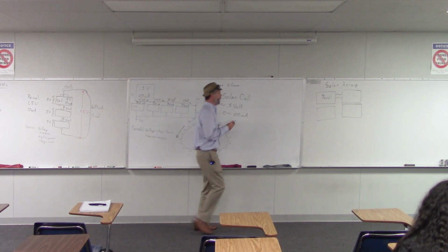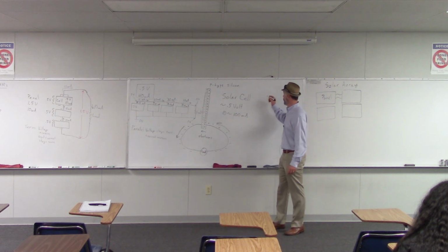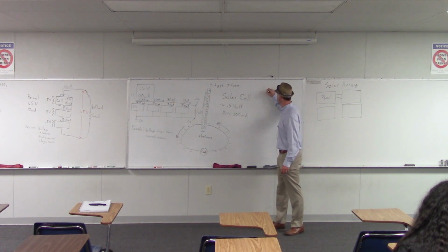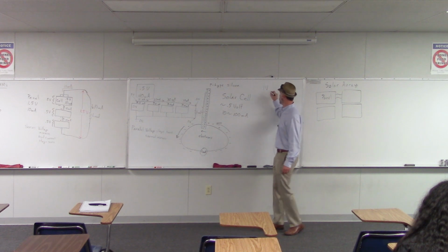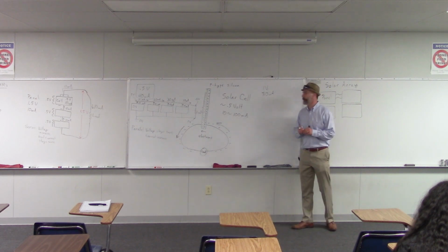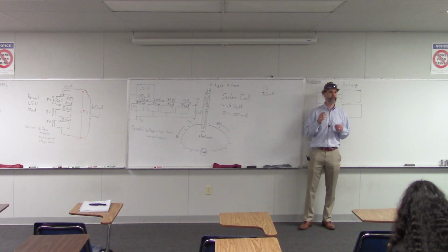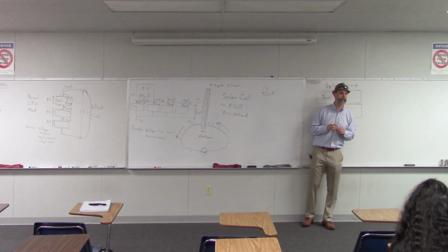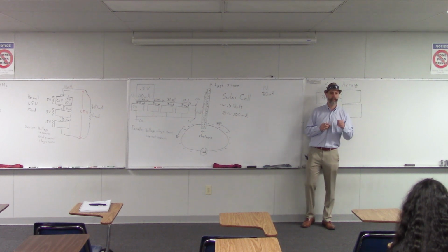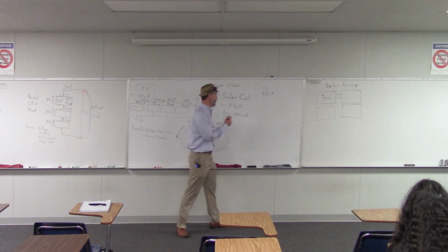So say you wanted to have a panel that produced 1 volt and 30 milliamps. How could you do that? Make 3 arrangements of 2 cells in series and then wire those arrangements in parallel. Yeah, that's perfect. That's exactly right.